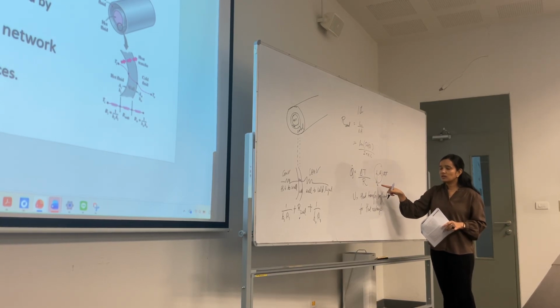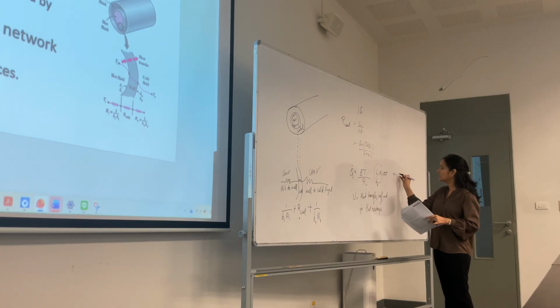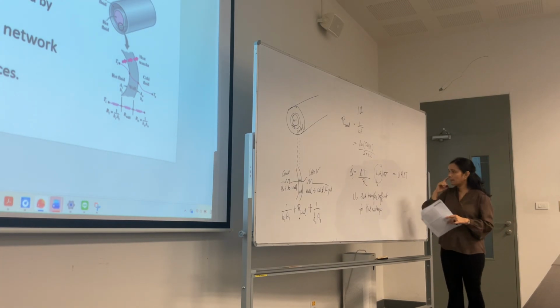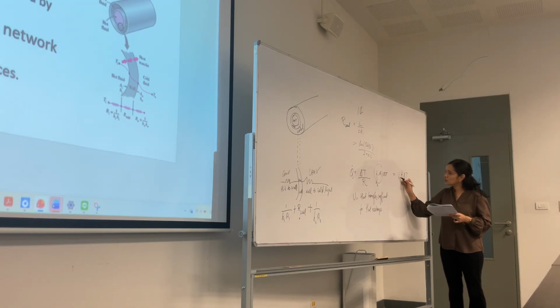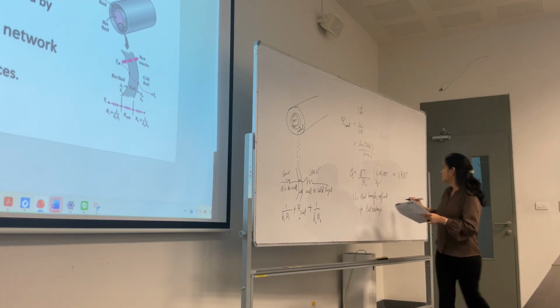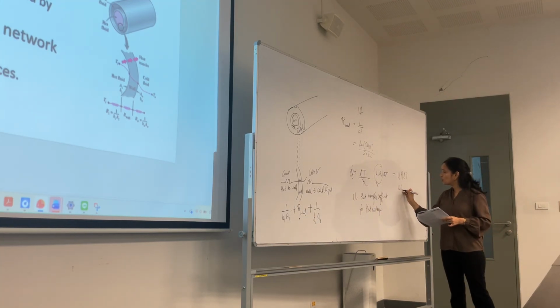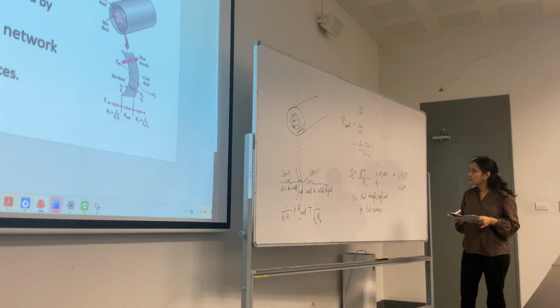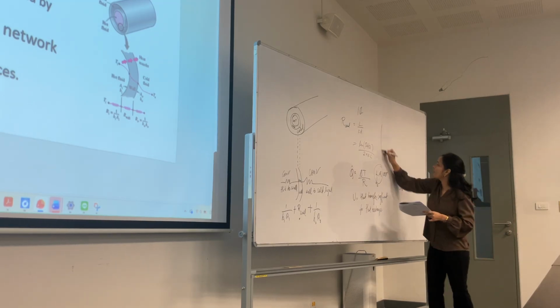Transfer coefficient for heat exchanger. So I will write it as U A del T. Again, it will be UI AI for the inside, and UO AO, where O is outside, del T for outside. Okay. Now, very important thing.